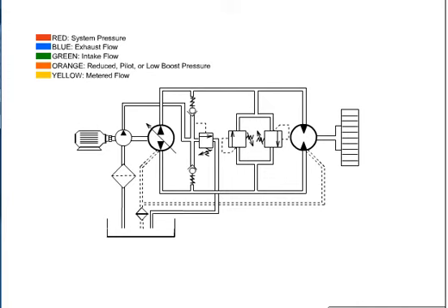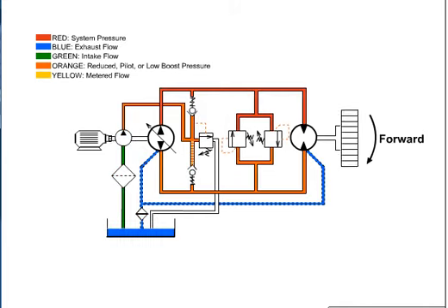In the last circuit, a fixed pump is added with a filter in the suction line, two spring check valves, and a charge pressure relief valve are added, and a heat exchanger is added to the leakage line from the pump and hydraulic motor. The fixed pump replenishes the hydraulic fluid that is lost from internal leakage from the pump and motor through the spring check valve into the low boost pressure line. The other check valve keeps the high system pressure isolated from the low boost pressure.